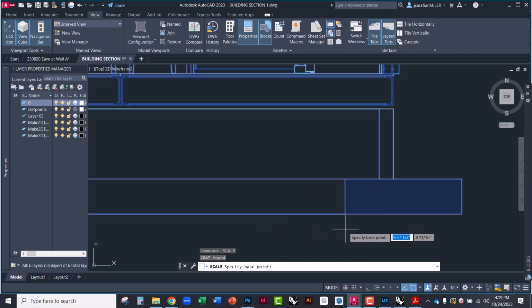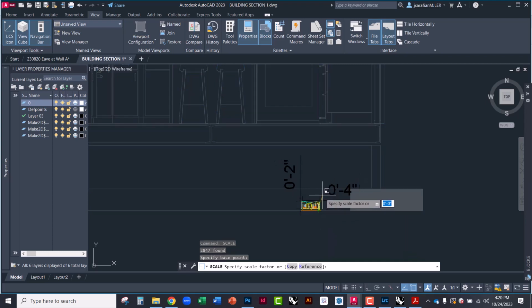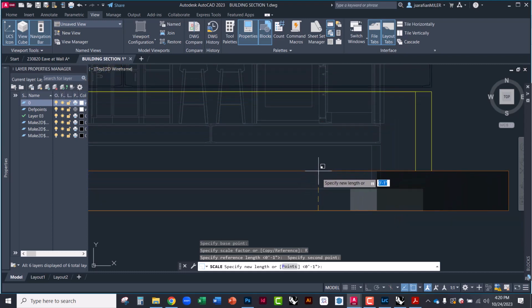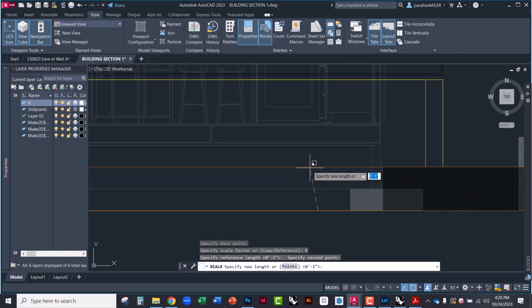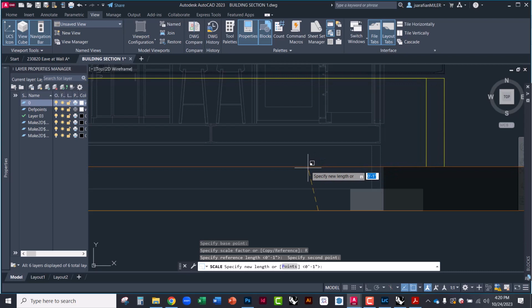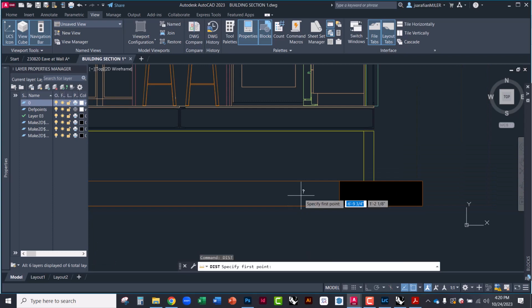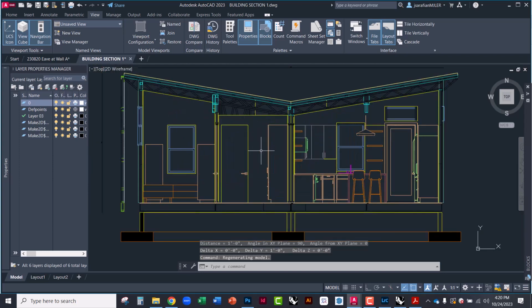And when you scale in AutoCAD, there's a couple ways to do it. You can scale with a reference. So I can click once, type R, enter for reference, click, click, and again it's asking for a reference. So it's saying, okay, those 2 points that you selected, what's the actual distance there? So I'm going to type 1 foot, enter, zoom out, and now when I type distance, or DI, it's giving me 1 foot as that distance, and it just scaled up the whole drawing accordingly.